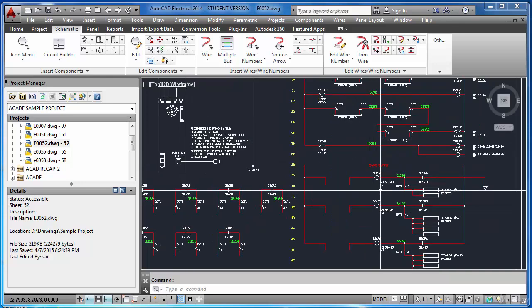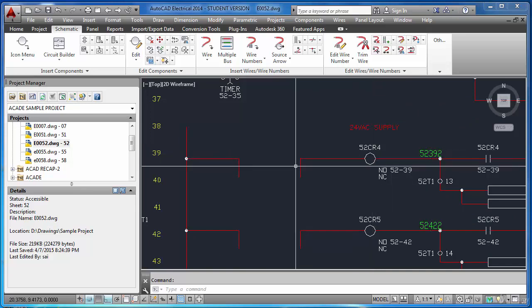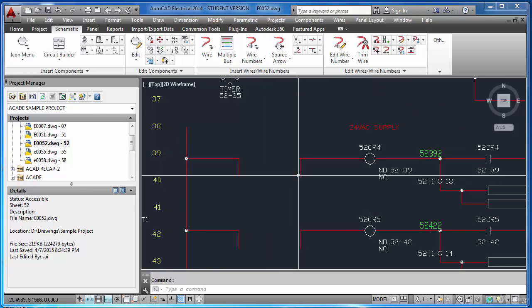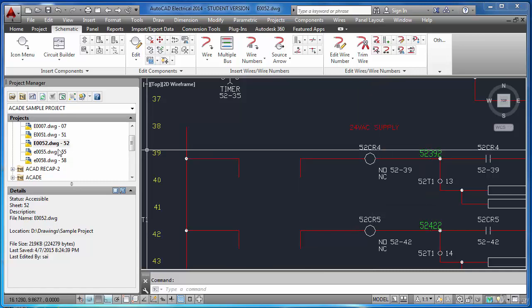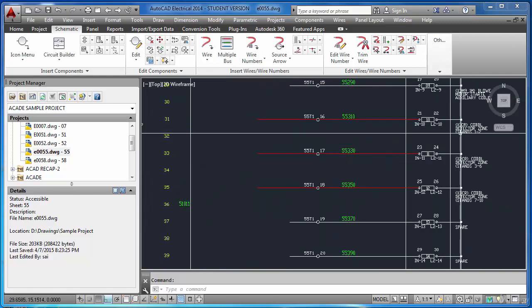And the same way, what we have to do is we have to provide a feedback. Once this is on, we have to give a feedback to the PLC also, that is input. That should go to the input card saying that yes, this is on. So we should give one NO contact of CR4 to here.